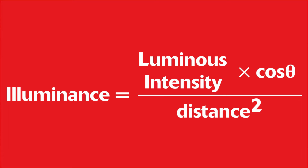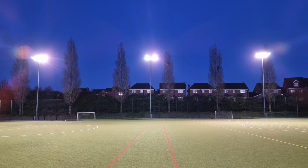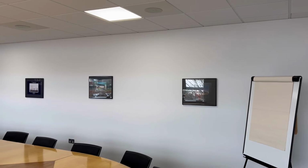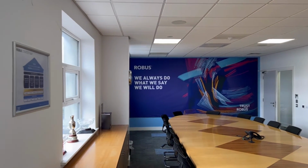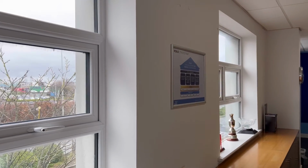Now, these calculations combined are all good for large indoor spaces and outdoor lighting installations, but for smaller, more complex indoor spaces, we need a different method. This is because as well as light travelling directly from the source to surface, it also bounces off the internal walls, ceiling, and even the floor. All these surfaces will absorb and reflect different amounts of light. And then you add in windows where light will both exit and enter the space, and our simple inverse square law becomes hopelessly overwhelmed.